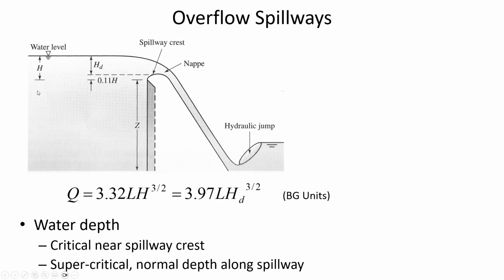So if we look at water flowing over a spillway, the nappe is the shape that the water would take if it was flowing over a sharp-crested weir, and we try and simulate that shape both because it increases the efficiency of flow and also it enables us to, in some sense, react to higher or lower flow rates by maintaining a more constant head level.